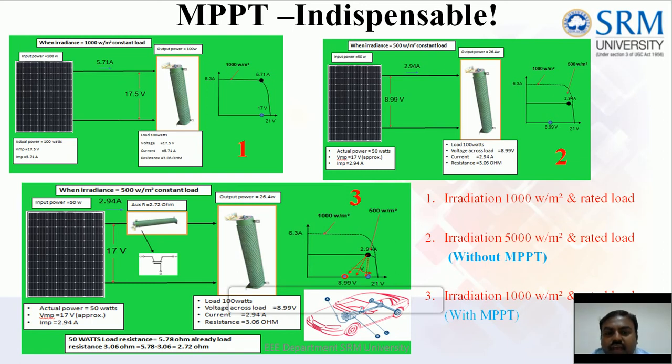So here I am using a series resistance so that my effective voltage is adjusted so that I get 17 volts, so that the remaining power of 24 watts is yielded. So by adjusting my resistance, I am getting the 24 watt power what I lost. So the conclusion is, you should adjust your R Thevenin if your RL is fixed.